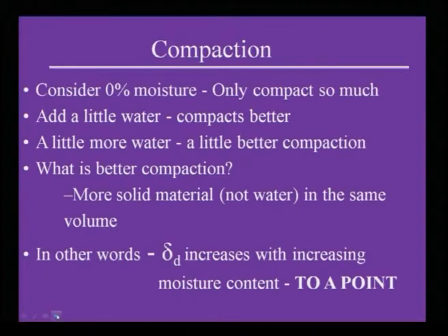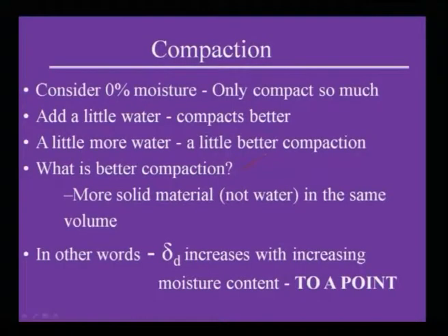So, let us consider 0% moisture. With 0% moisture, you can only compact so much. Add a little water, and it compacts better compared to 0% moisture. Then more water, a little better compaction. What do you mean by better compaction? That means more solid material, not water, in the same volume.